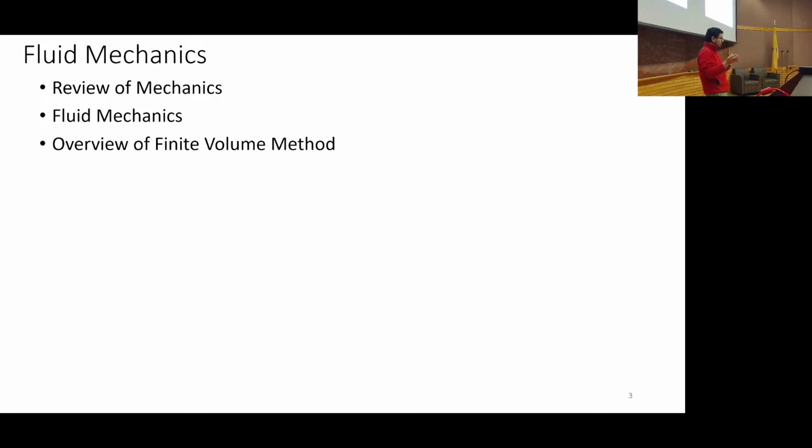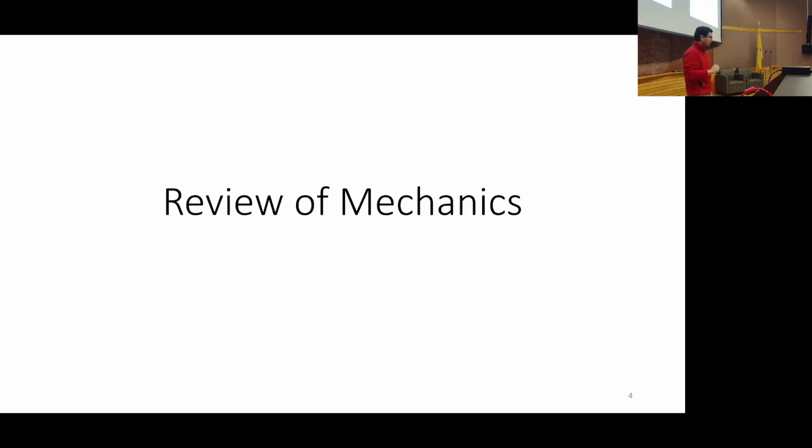In fluid simulations, we care a lot about the velocity profiles, and we care a lot about drag. So we're going to care about forces. We're going to care about the shear stresses or the normal stresses on a surface that create forces, the lift and the drag on an object. So we're just trying to connect some of these dots. Okay? And then the finite volume method, which is very powerful when used appropriately.